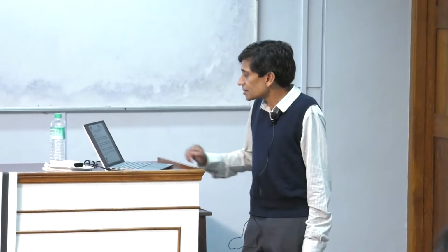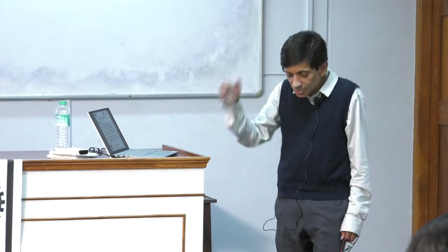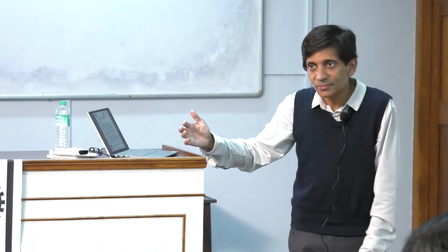All right, so I've talked about these limitations, and that's about where we got up to yesterday. So the main point here is the importance of lateral permeability, as it's called, so the flow from the sides. That's very important, and the importance of asymmetric membranes as opposed to track-etched membranes. So this brings us up to an interesting point, so-called symmetric and asymmetric membranes.